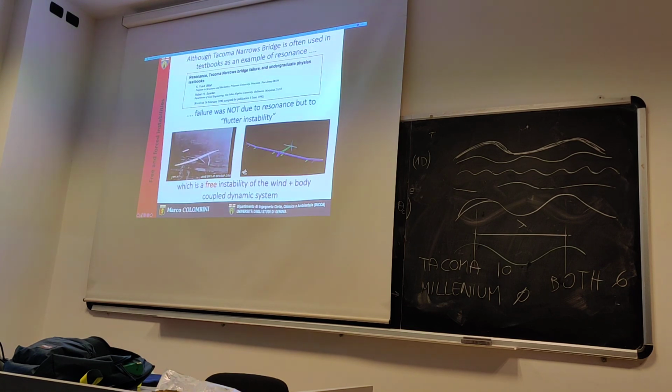As opposed to that, a forced instability in bed forms is what you have in meandering. You can have bed forms which are forced by the curvature of the channel. You can have free bed forms inside the meandering channel, but you also have a solution of the problem, a form of the bed, a pattern, which is related to an external forcing, which is the curvature of the channel. So if you study a steady meandering channel, one in which the banks are not changing in time, then this is an example of a forced solution.